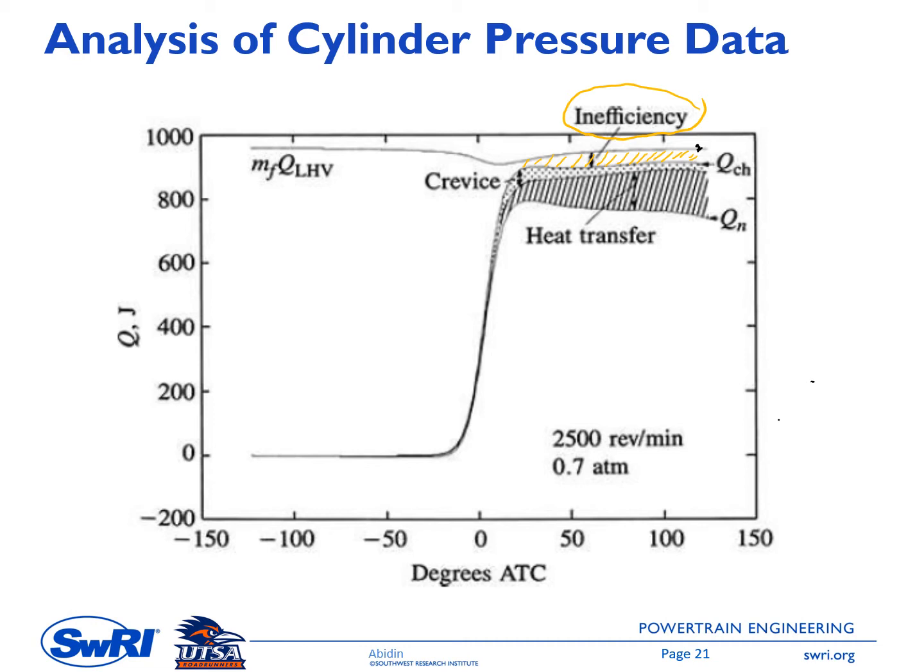We have a high combustion efficiency inside the diesel engine because of the lean mixture combustion. We have a couple percent unburned hydrocarbon inside the gasoline engine. And then the next one, represented by the black dot here, let me select this and make it purple. Okay, this one represents the energy loss because of the blow-by.